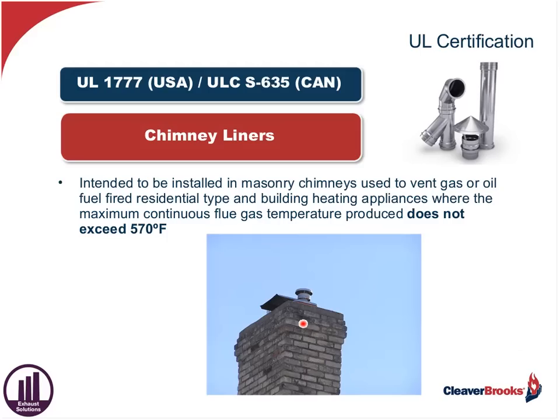Now for those in the United States, the UL certification number is UL 1777, and in Canada it's ULC S635 for those liner materials. And of course, in those particular situations that are certified by UL, we're looking at temperatures that would not exceed 570 degrees.